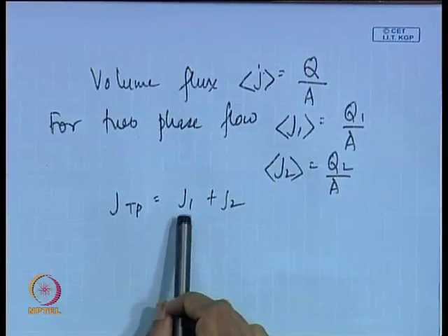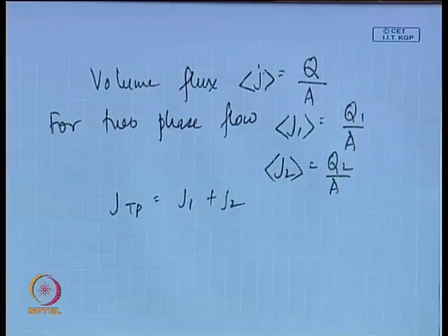So, by definition, they are not the same, and volumetric flux is a vector quantity, but for the present situation it will be used exclusively to represent the scalar component in the direction of motion along the pipe. And therefore, under such conditions it is numerically equal to the superficial velocity of the individual phase, but the basic definitions are different.